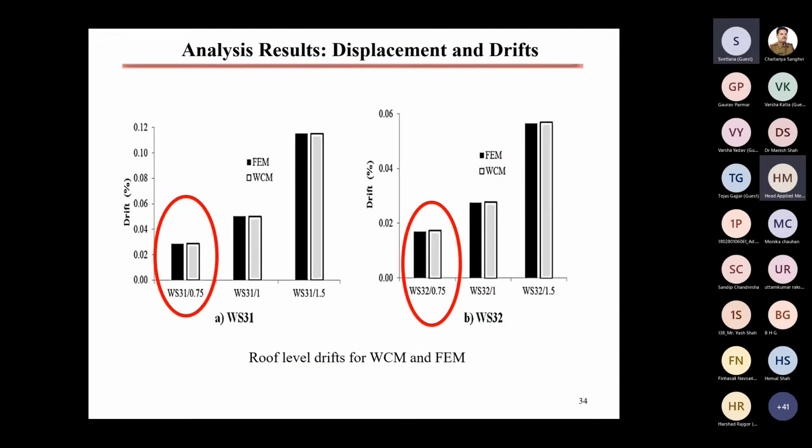And on the next slide, we have differences in displacements or drift level for these models, and you can see this circled is the model that I've shown before. So you can see practically there is very little difference in both. There is some difference, but very little in displacement. So definitely the wide column model can simulate very well. I mean, it's very similar to the finite element model. We are not claiming that the finite element model is absolutely accurate, but let's say it is a more accurate and more sophisticated modeling approach. So that is for sure.